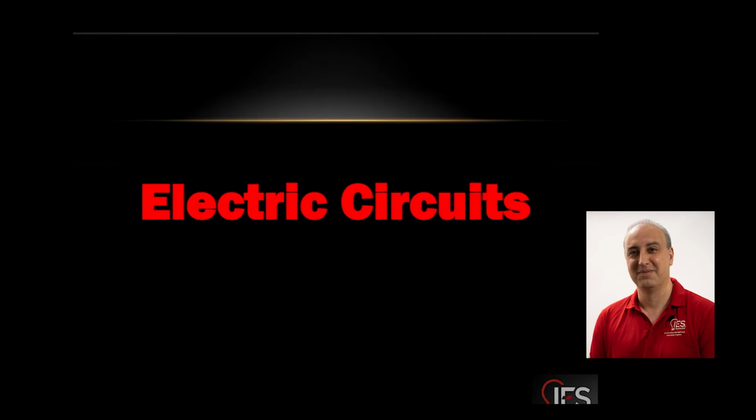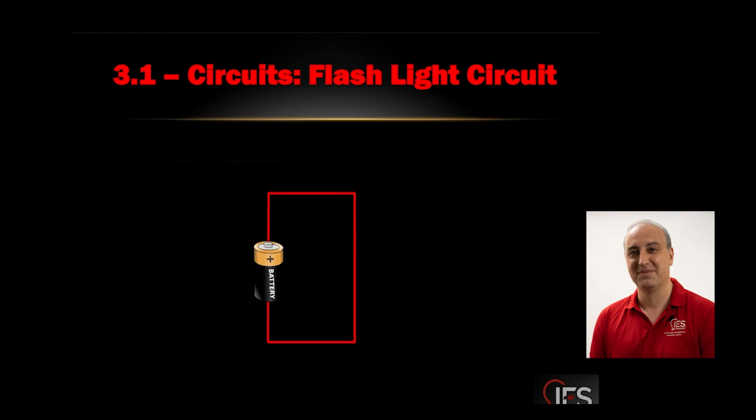So today we're going to get into actual circuits. We go back to the battery example. It's easier to see things in DC and then move into the AC domain. When we connected the battery by a piece of wire, now you understand resistance is the friction of the wire to the movement of electrons. If you connect the two ends, we call that a short circuit in electrical terms, right? Short circuit means it's a very low resistance path that we've created. So we get a very high current, it heats up your wire, and usually if it's a battery, it kills the battery pretty quickly. You might see arcs flying. If you've ever tried to charge your car battery and accidentally touched the positive to the body or a negative terminal, you see a spark come out. Those are examples of a short.